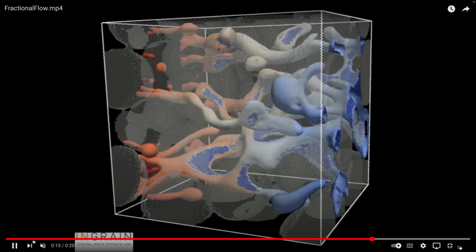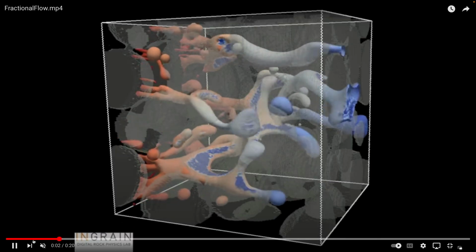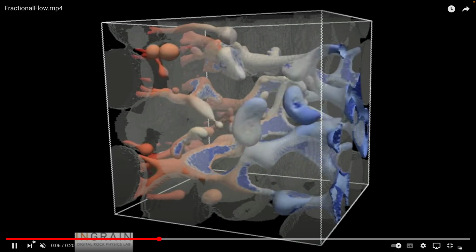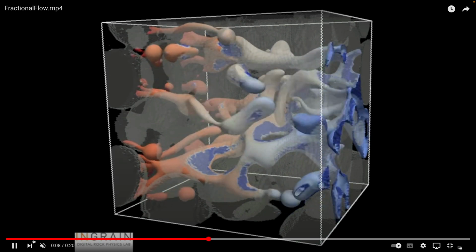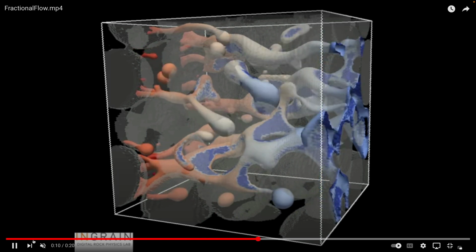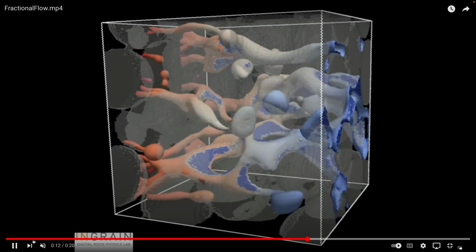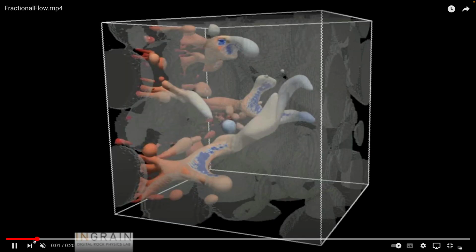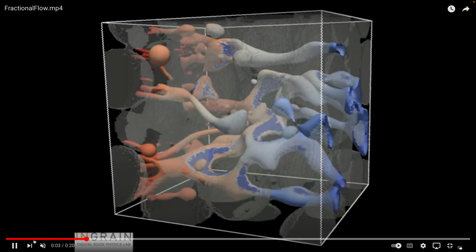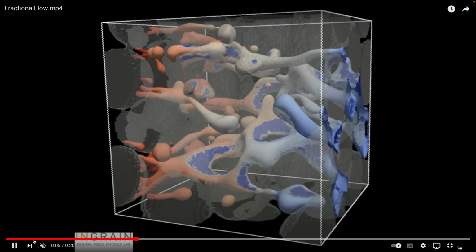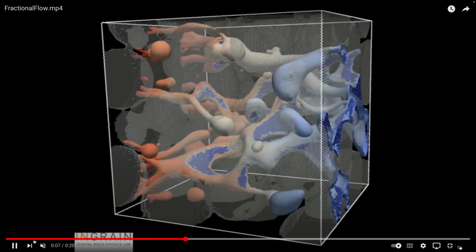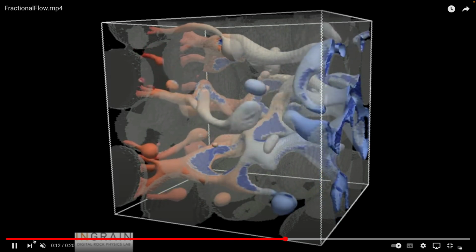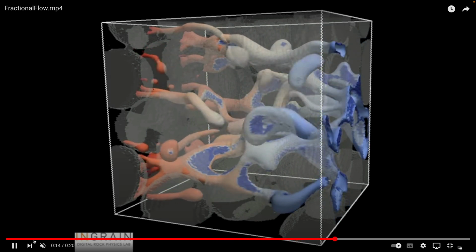And so one thing that you could do would be to look at applying a pressure upstream, a pressure downstream, measuring the amount of fluid that comes out of the bottom, and defining that as what we'd call Darcy's law. If you've seen it in any of your courses, you certainly will in almost all of your majors, to understand exactly what the physical properties are. And Darcy's law is an empirical law that says if you double the pressure differential between upstream and downstream, you double the flow rate coming out of your cube.